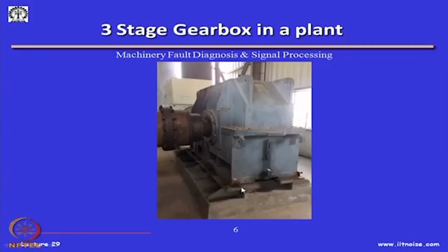And in fact, you will see a lot of corrosion occurring, and many times because of this corrosion, the gearboxes will lose their alignment, and then the bearings will get unnecessarily loaded because of the heavy loads, and they will be rotating under load. So, you can imagine it is like a domino effect, one leads to the other.